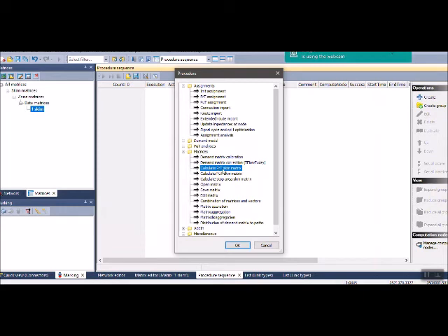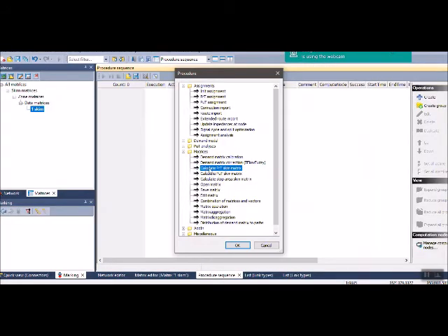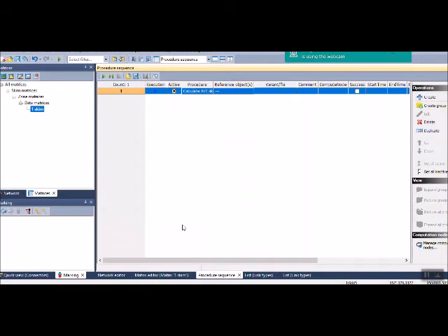We are going to deal with passenger car units because in this example we have our demand matrix in passenger car units, and this is the simplest form to deal with any type of vehicle. We are converting any type of vehicle to passenger car units. So we choose calculate PRT Skim matrix, and select OK.